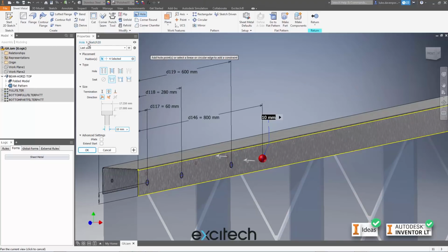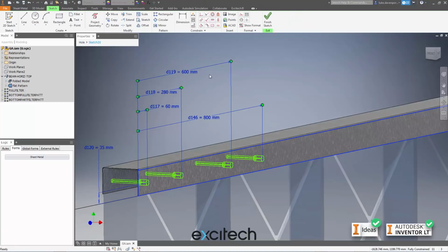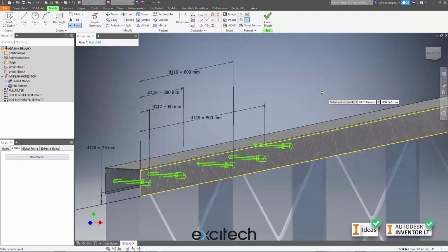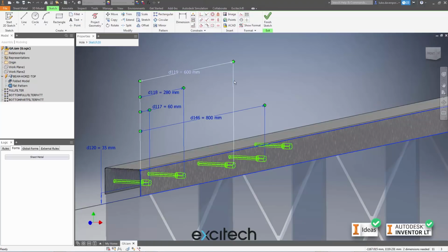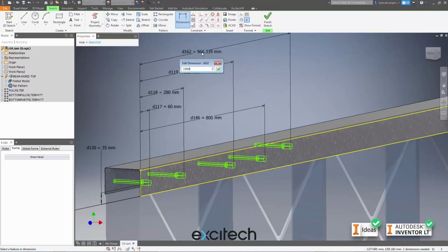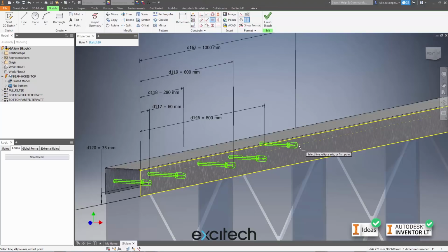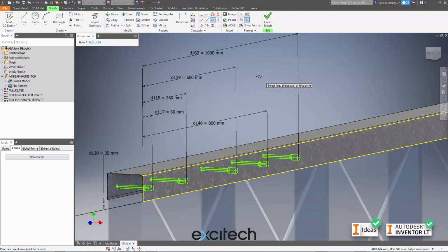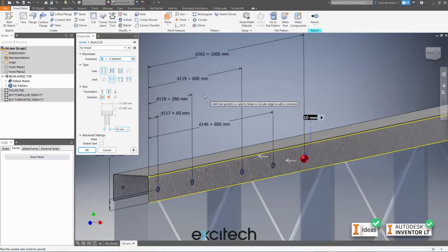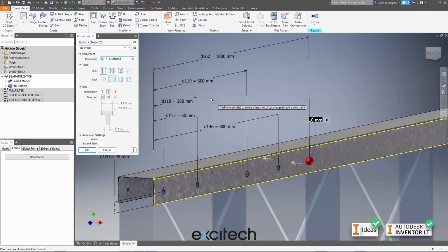I've got breadcrumbs up the top here, as they're called. I can click on this sketch here and directly edit the sketch that has been picked up for the holes. So if I start the point tool here, I'm in my normal sketch environment. See, I've got all my normal sketch tools here. I can dimension from whatever points I need here, put constraints in, same as usual. Sketch is fully constrained. How do I get back to the hole tool? I just click on hole here. So I can toggle back and forth between the hole and the sketch it references, which is fantastic.